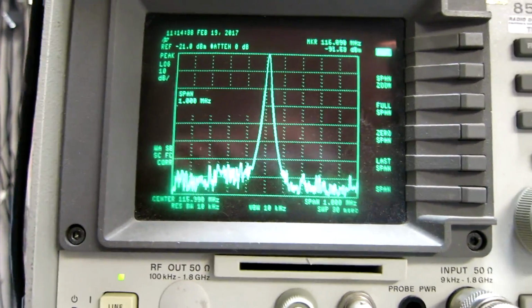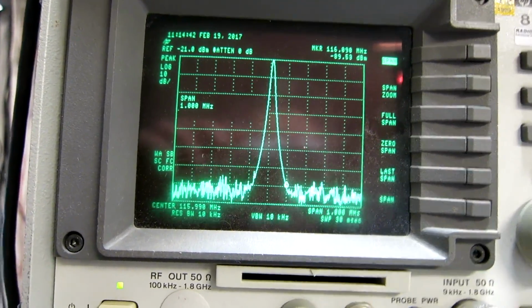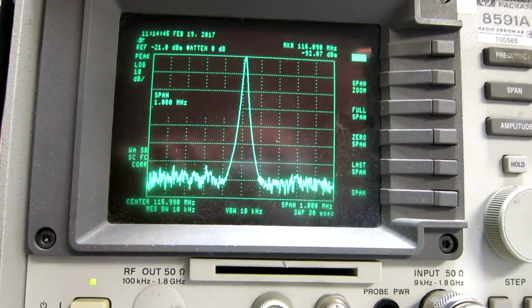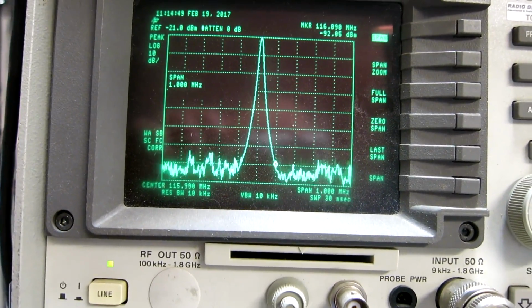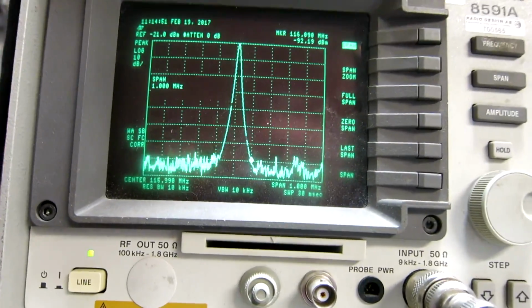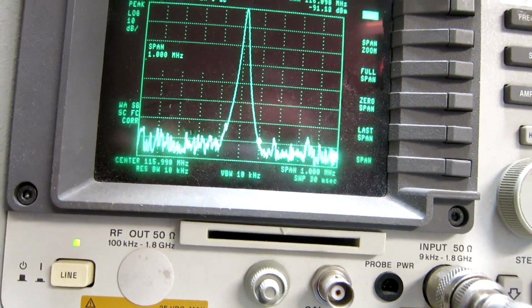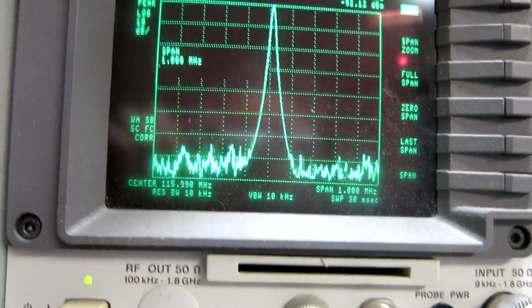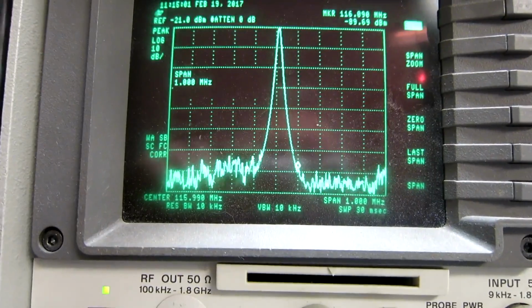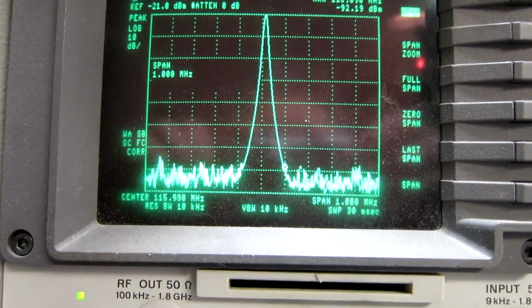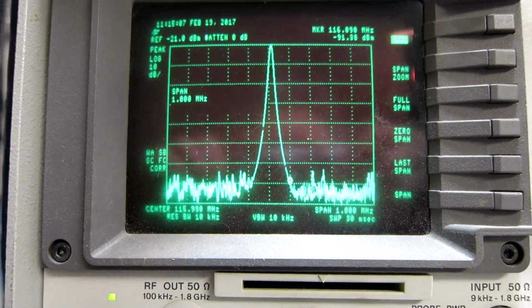When looking at the wider frequency range and with 1 kHz video resolution, I can see on the noise floor that it jumps up and down by nearly 10 dB. I don't know the reason for this, but before trying to eliminate it, I will see what the average level is by going back to the narrow range and slow video.